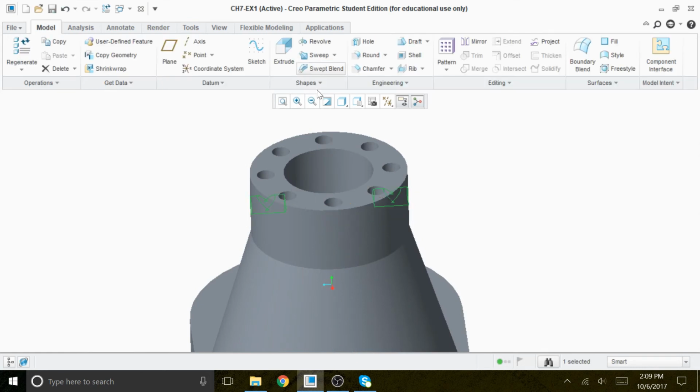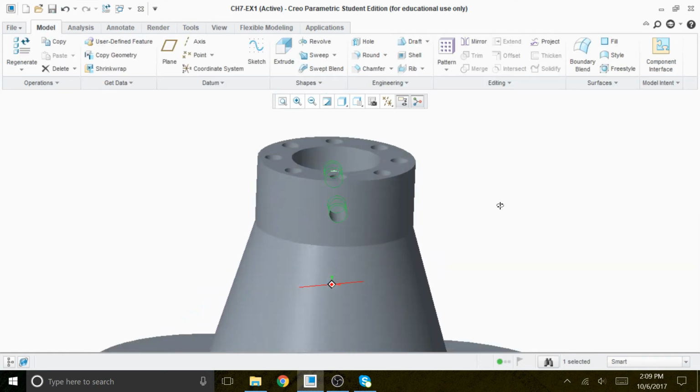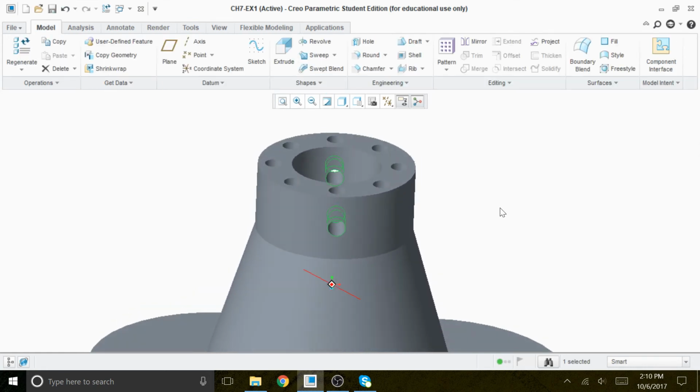So we're going to check it. Now we're going to create what? We're going to pattern that. Okay, it's supposed to be 6 holes, but look at this technique. Instead of showing 6 holes, I'm going to show 8 holes, but I'm going to remove 2 because we only need 3 holes on this face and 3 holes on the back side.